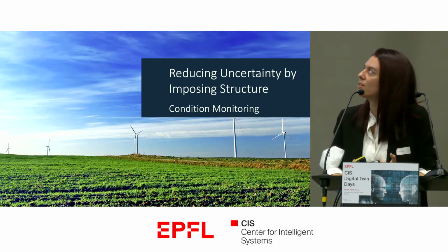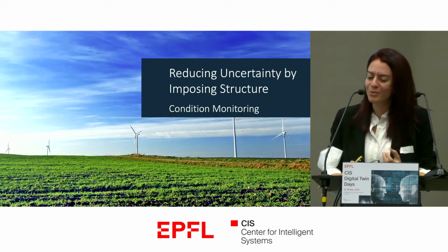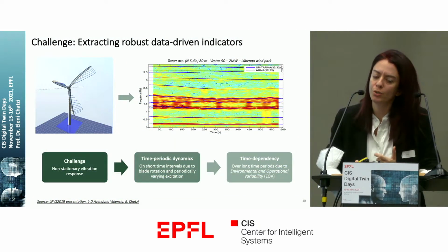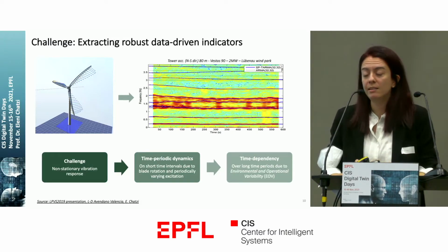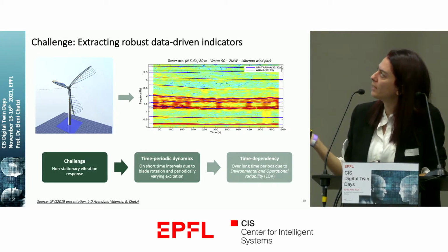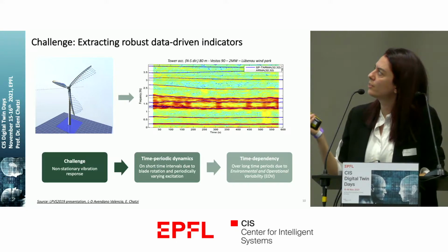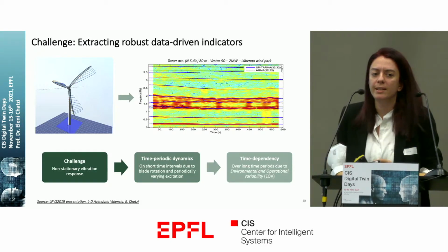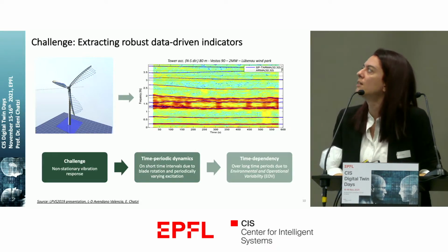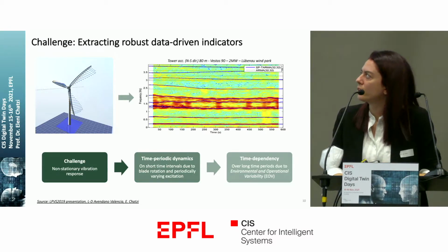And I would like to start by explaining how to improve our prognostic or diagnostic capabilities by infusing some sort of structure into our representations. So here again, I show you this example. I'm staying in the same use case, monitoring for wind energy infrastructure, where the type of data that you would obtain from really low-cost acceleration measurements would look like this. This is over a time frame of about 10 minutes, and you see how the dynamics of the system is actually varying even within these 10 minutes. And this is because of the type of loads that the turbine is exposed to, but also because of the rotary dynamics of the rotor itself.